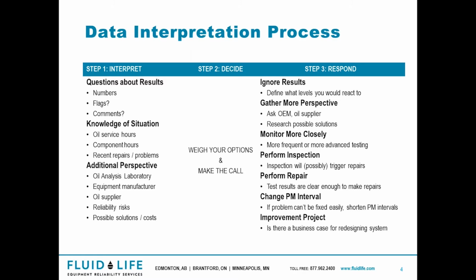And respond can show up as a number of different things, whether that's just to ignore the results and wait for the next step, or gather more perspective. Ask your outside sources for some help. Monitor more closely with some more testing or different testing, perform inspections, or actually react to those results, whether that's oil changes, filters, or any other additional resources you may have to solve the problem represented by the oil analysis results.